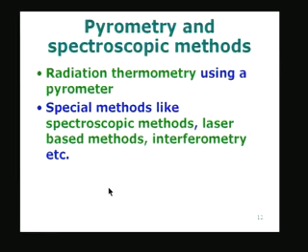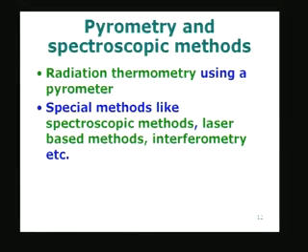And if you remember or recall the ITS 90, we said that above the silver point, temperature is measured using the radiation or the black body radiation law, which is basically Planck's radiation function, and in fact, the radiation thermometer uses what we call a pyrometer.